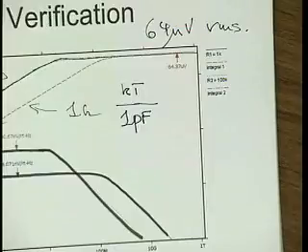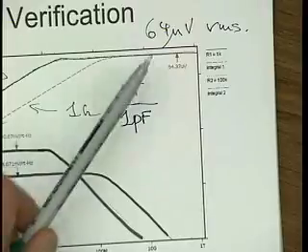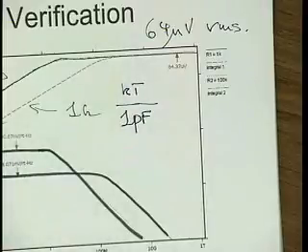And if we wanted to cut this down by a factor of 2, if instead of 64 microvolt RMS noise samples we would like to have only 32 microvolt noise samples, how would we change C?